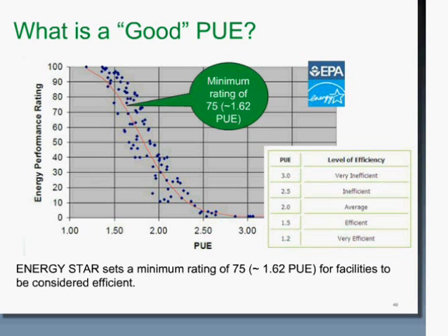So in total, that's a snapshot of what we've done from a branch circuit monitoring and power quality standpoint, and also some information in regards to calculations of PUE and some of the benefits of having an installed metering and monitoring system. And I think these trends are very important as data centers move into a lot more colo applications, where billing, sub-billing, and tenant metering become much more important. So we'd like to open it up to any questions.